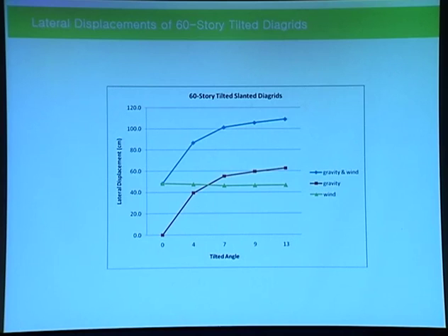And in terms of the wind load induced lateral displacement, the tilted tower employing diagrid structure is not substantially changing depending on the angle of the tilting.